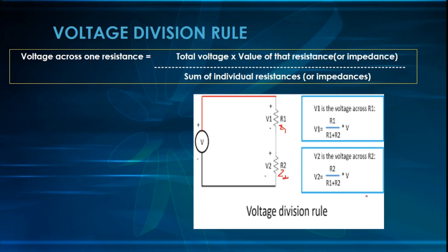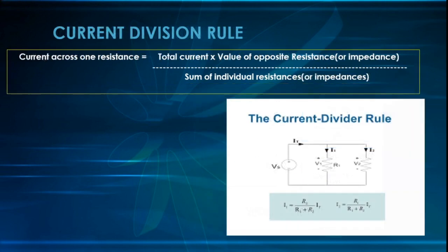So a DC circuit contains purely resistance values. For an AC circuit, it will be a combination of R, L and C, and that is what we represent as impedances in the circuit. When components are connected in series, keep in mind that the voltage gets divided and the current remains constant. That is why we have the voltage division rule in a series connection.